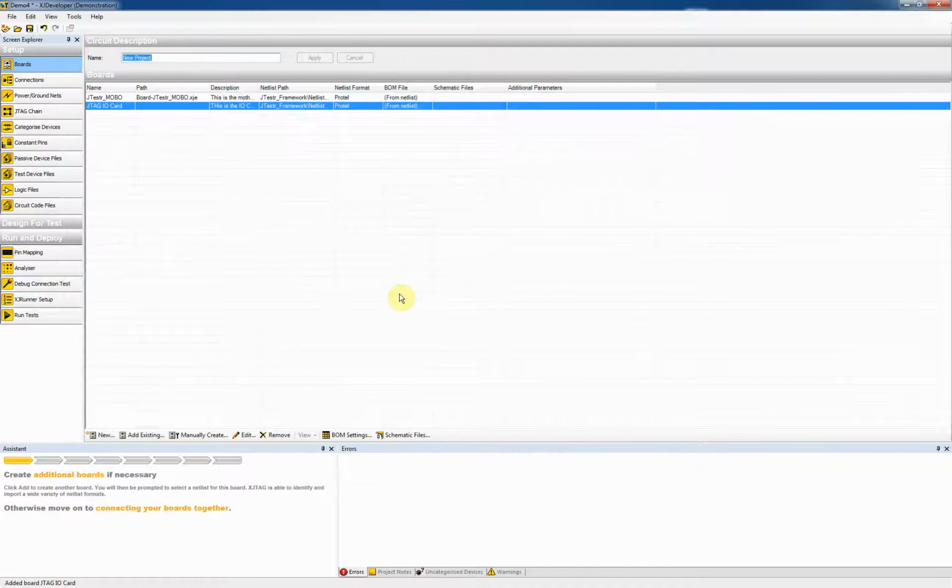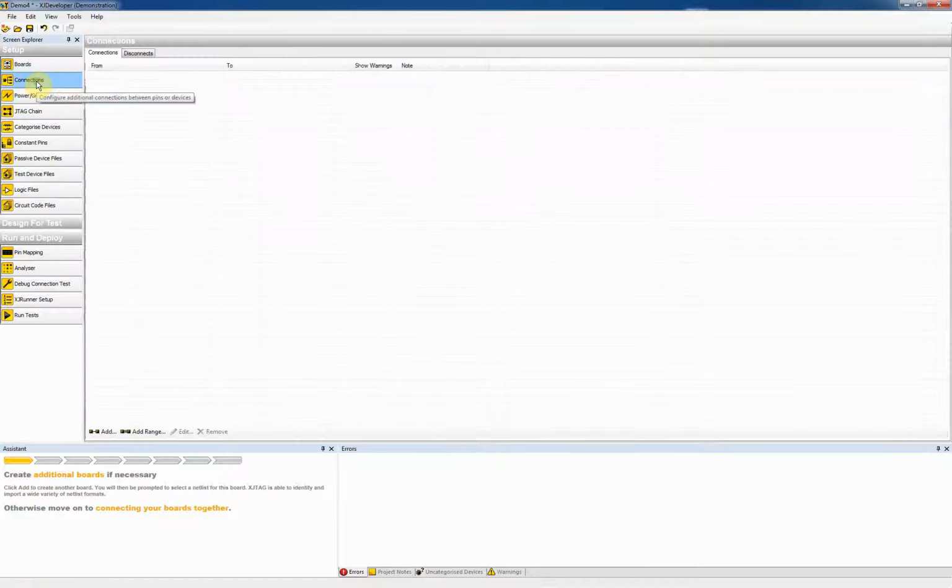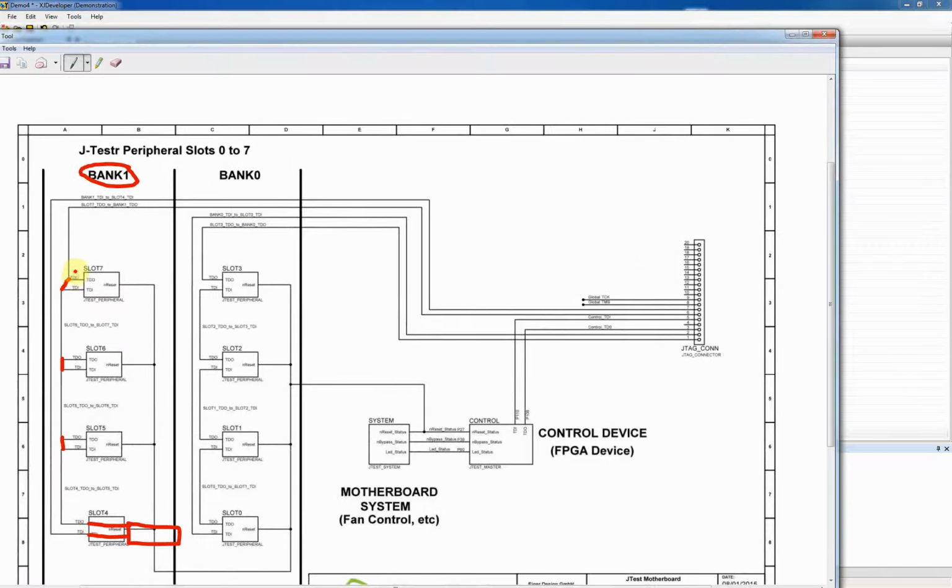If you wish, you can go to the I/O peripheral card instructions, and you can get the overview schematic which is used to generate the netlist which we've loaded here. Next, we need to make the connections we talked about when we viewed the schematic earlier. So just to bring that back in, we need to make these connections here to bypass the slots that we are not using.